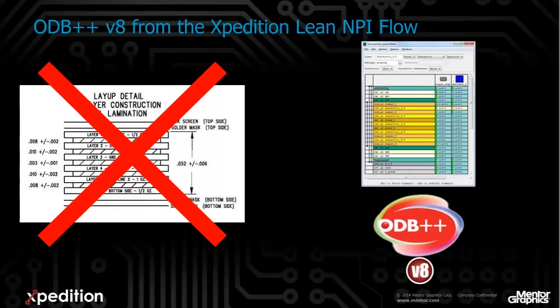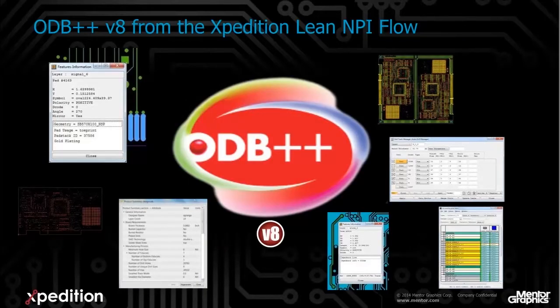The stack-up drawing data is included in the ODB++, shown here with examples of the dielectric requirements, including bulk resistivity and loss tangent for the insulation layers, and the copper weights for the conductive layers. When a complete product NPI process has been carried out, there is much more to the ODB++ than being an alternative to Gerber. Instead, it delivers a complete definition of what has to be manufactured, including all of the information traditionally carried in paper or PDF documents, but now integrated into the structured data ready for immediate and automatic use by the next software tools in the flow.